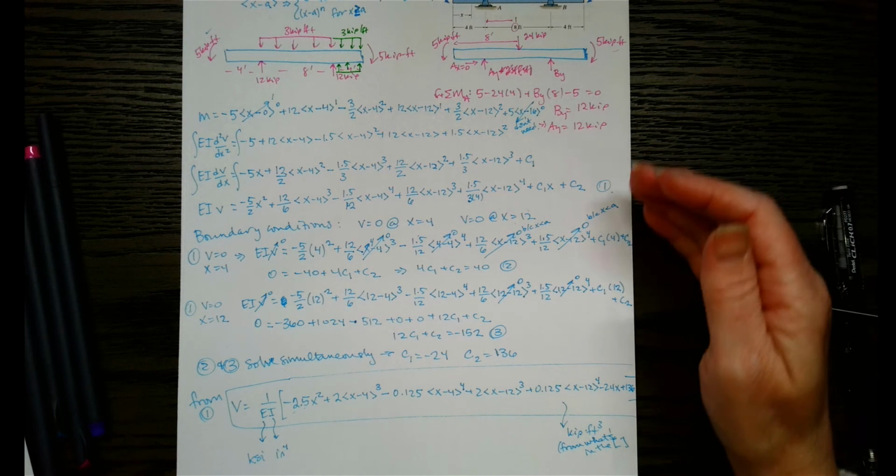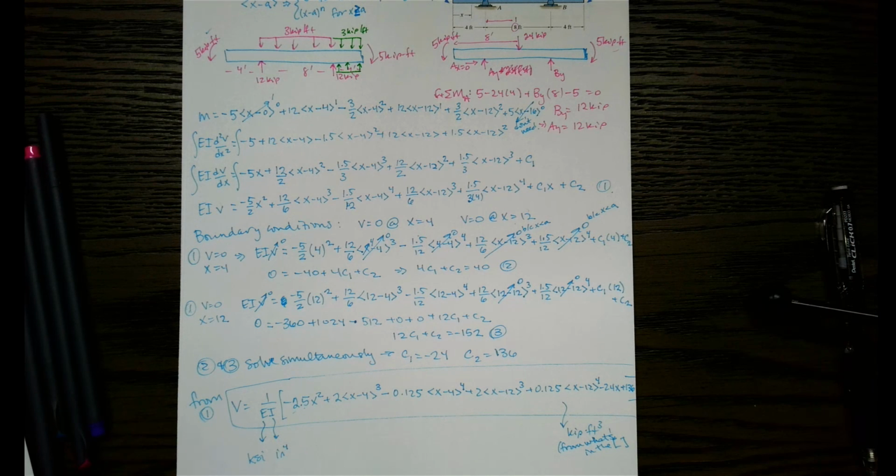These problems aren't too bad. They get kind of long though, as y'all can see, because this is a 30-minute video here. A little longer than I anticipated, but that's what we got. Okay, so that gives you your equation for the elastic curve. And basically the elastic curve shows the deflection of the beam. So you could go through and basically plug in x values here and get the deflection at certain values of x along the beam.